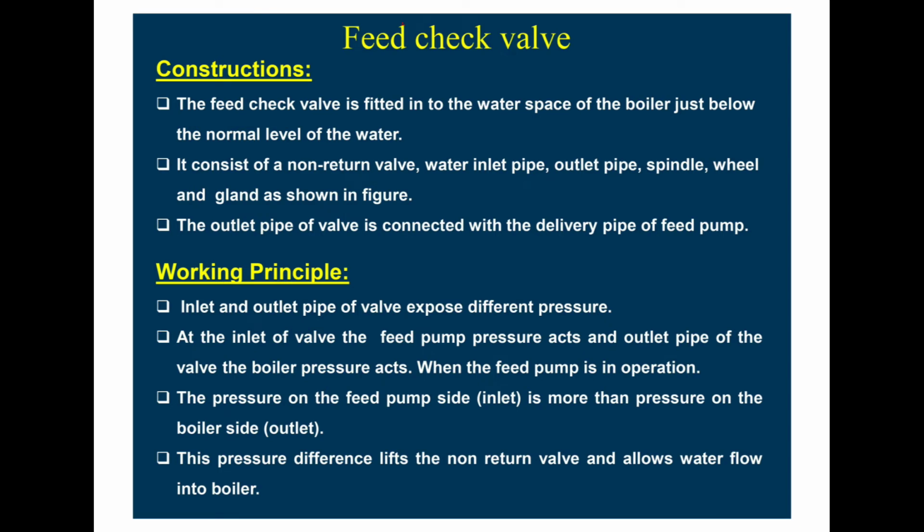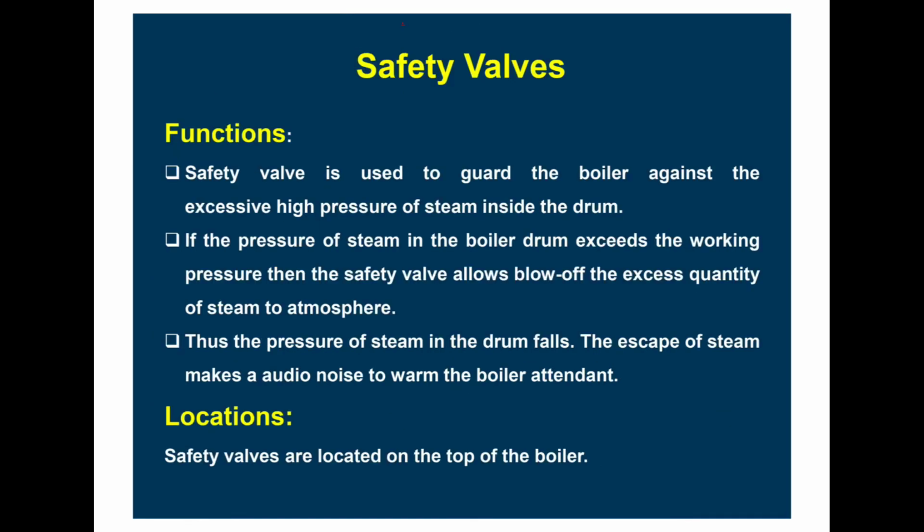The working principle: the inlet and outlet pipes of the valve experience different pressures. At the inlet of the valve, the feed pump pressure acts, and at the outlet pipe of the valve, the boiler pressure acts, when the feed pump is in operation.